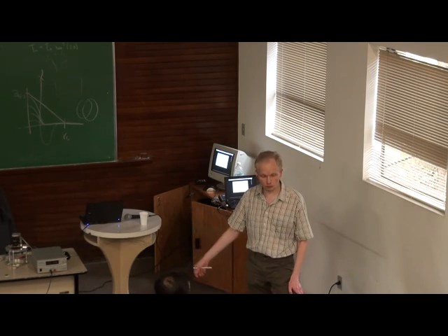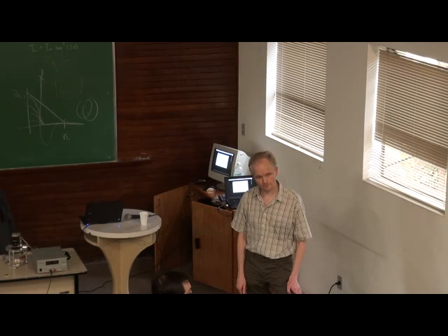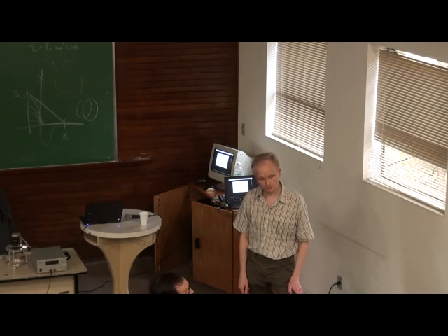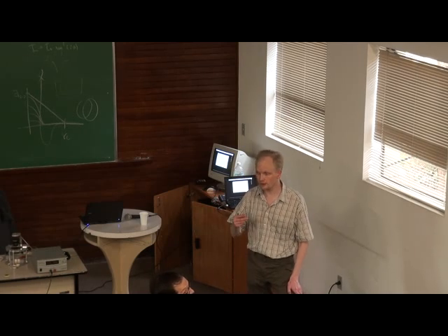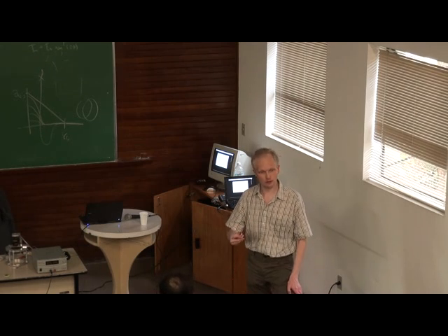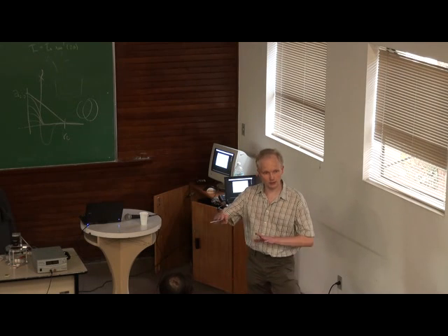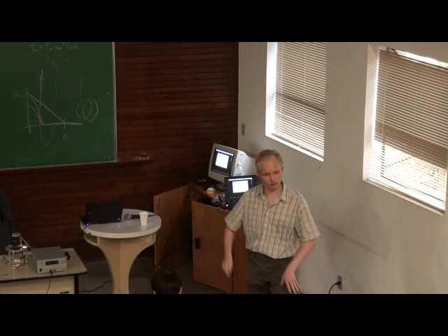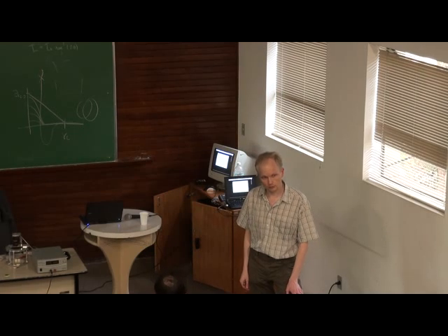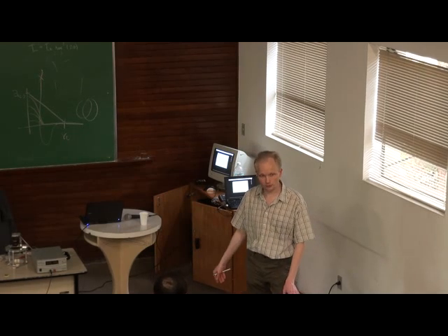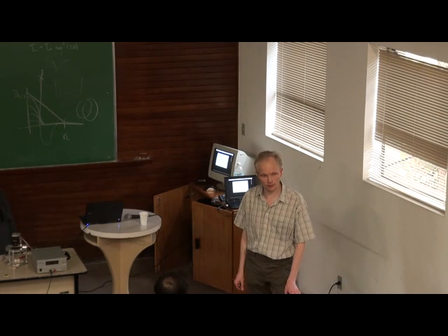You select the equation and put in the parameters. You specify the kind of interaction potential that LAMMPS already knows and the interaction parameters. And of course, if you have many types, you have to specify all the cross terms also. If it doesn't exist, you can implement it yourself. It's not terribly complicated to add more interaction potentials.